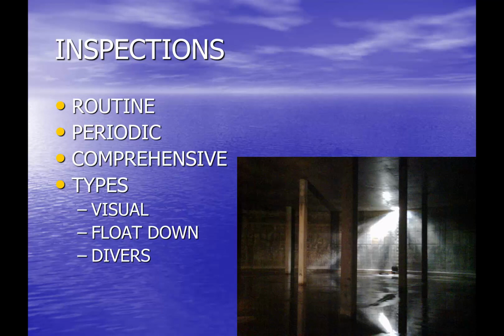There are underwater epoxies. If you've got a coating failure, maybe there's one particular place where it looks like the coating is failing, there are underwater repair mechanisms to do that, which you can accomplish without taking the reservoir out of service. We talked before about the sediment removal that you can do with divers. There are a lot of companies out there that do these dive inspections, and it's an important way to ensure the integrity of the reservoir. And then ultimately the most aggressive is to literally drain the reservoir and to go inside.